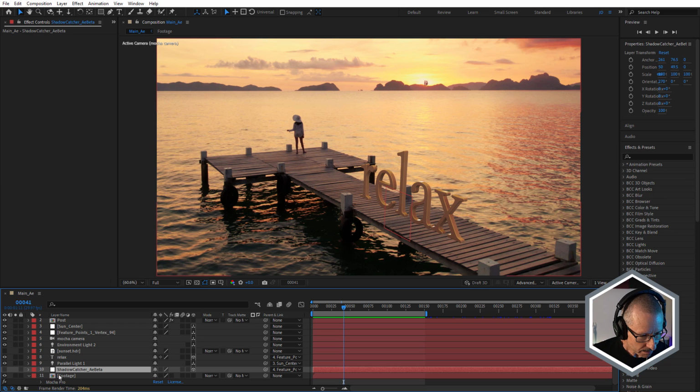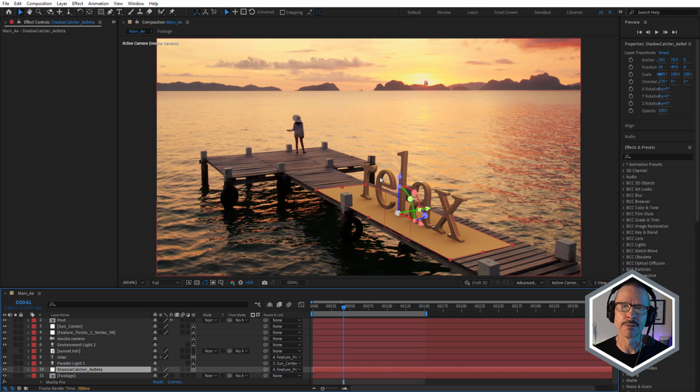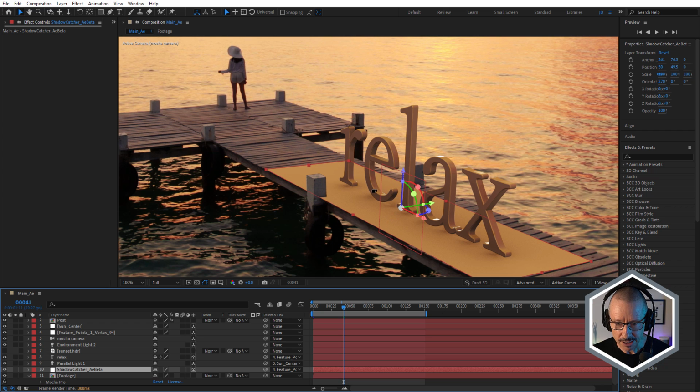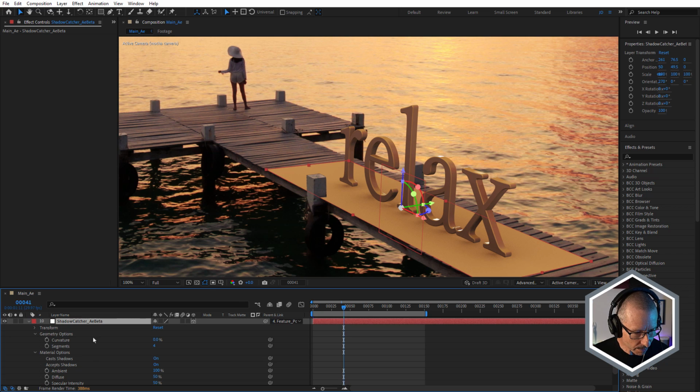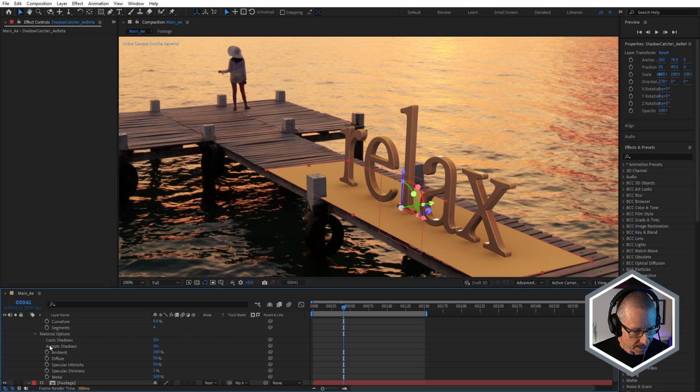So we've got a layer here, and I'm not in the After Effects beta at the moment in this version. This is the release version. So I can create a shadow on this solid, but I can't use the solid as a shadow catcher. If I just twirl that open, you can see Accept Shadows is on, but Only is disabled. So as soon as I click Only, I lose my shadow.